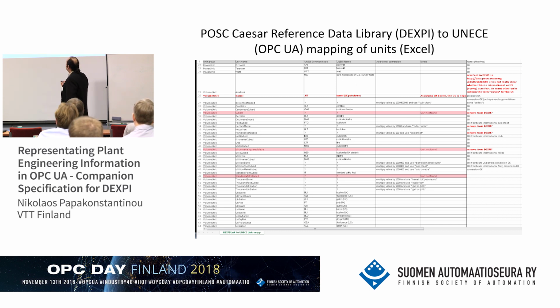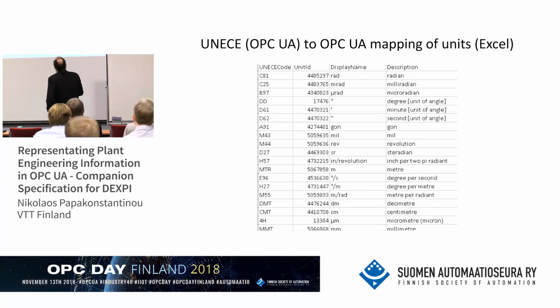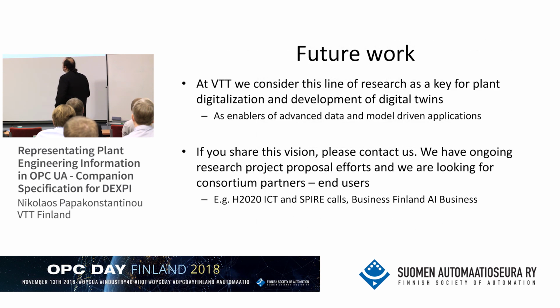And sometimes we have to define transformations, because we don't have the exact unit, but we have something that, if we multiply, divide, or do some transformation, we can get. And then we have a different mapping between the United Nations units and how they should be in OPC UA. So a third information source comes into the picture. But anyway, these things are not very big issues, and the engineering units part is already under consideration by the OPC Foundation.